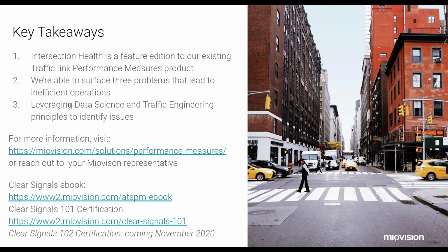And then the progression quality is coming from just the signal phasing and timing information. So we're taking that, we're lining that up, and we're creating the green bands in both directions, and we are assessing the quality of that green band. If we identify that it's either very inconsistent or very low, we alert on that. So basically, stop bar detectors and signal phasing and timing coming from the controller would be required in order to have this functionality.